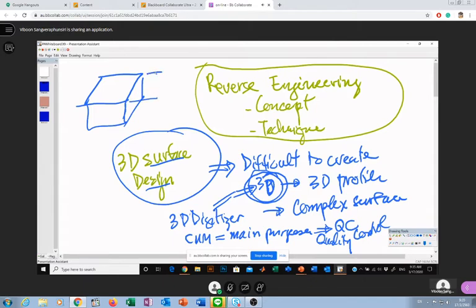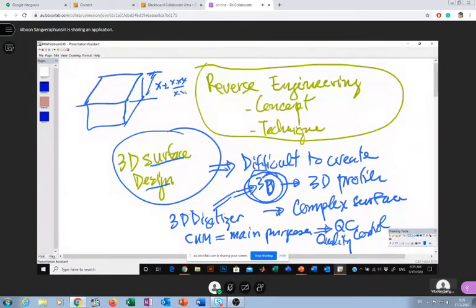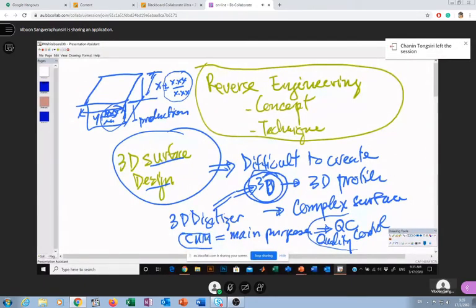and you have some tolerance control. Let's say you have this dimension plus or minus. This we call tolerance. This kind of tolerance, as well as this one, you need to have some tolerance as well. Even this one. So this is what you need to control your production. When you build this machined part, before you send it to your customer, you need to do some QC, quality control. So CMM is a machine that helps us do quality control of your machined part.